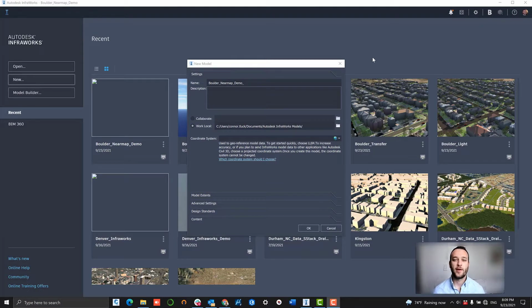Today I'm going to be loading up a full Nearmap content stack within the InfraWorks environment. So that's going to be high resolution imagery, 3D terrain data, and then vector AI content. Once our data is loaded up, we're also going to look into concept planning, workflow, material takeoffs, and quantity estimates, as well as a 3D rendering workflow as well.